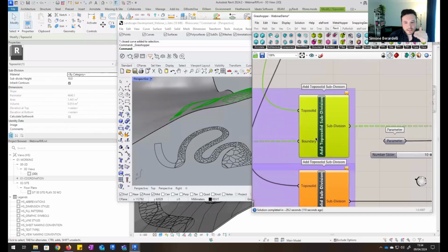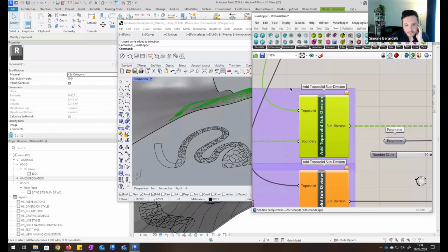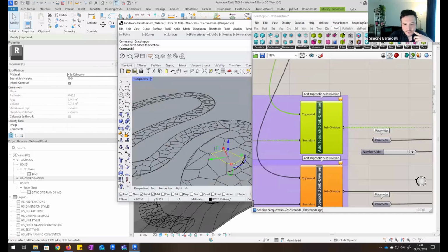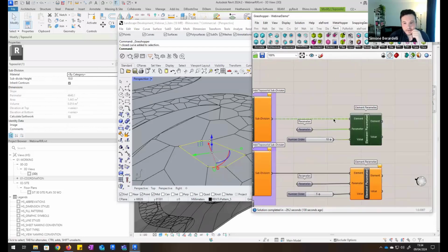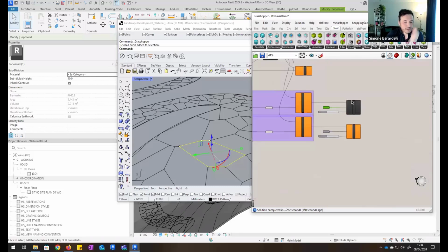The only condition that I need to respect is that the boundary needs to be an enclosed region. As you know, Revit is a bit picky with the sketches. It needs to be very strict on that. The Grasshopper script can do the job and create an enclosed boundary. That's why we trim those surfaces, as you can see here, as enclosed boundaries. And then I can specify, in this Rhino Inside node as well, what thickness I want to have in Revit. For now, I just put 10, for the sake of having a small tile. But it's all done through Rhino Inside.